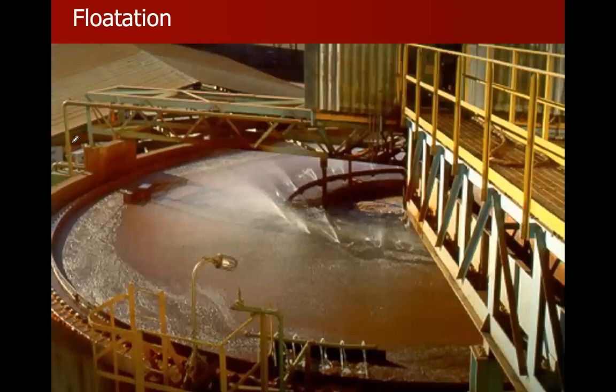And then flotation is taking place in some cases, as I mentioned. So the lighter ones get floated, right? Lighter materials are floating here, and heavier ones sink down into the liquid, and this liquid can be separately collected and treated to separate out those heavy materials. The lighter ones, if you need them, you can collect, or otherwise you can dump them out. It's one stage of separation.